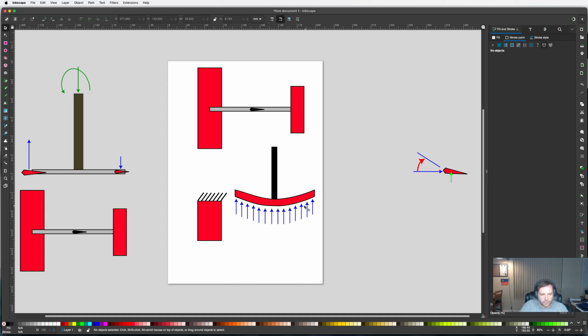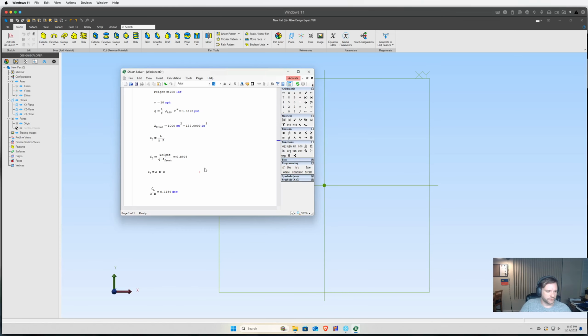It's going to have some span-wise flow, meaning the water is going to want to push towards the edge and roll around, which is why you get these vortices in the wingtips, because there's higher pressure here, there's lower pressure here, and it pushes the water around and creates that tip vortex. And that's why you see a lot of this change in the shape. Either you get winglets or you get changes in the profile at the wingtips to help get rid of this drag at the end. But for right now, for very simplistic sake, we're going to say it's a uniform pressure here. So we're going to assume that for ease of calculation.